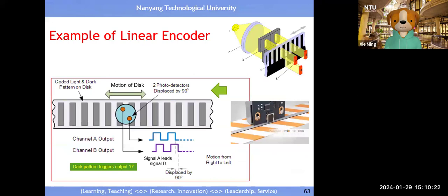Okay. Then you may want to know how to have a sensor which allows us to measure linear velocity, right? Then your design is like this, right? Same, okay? So then you will have a light emitter, light receiver, right? So you have a vertical strip, okay? You have transparent and opaque. Transparent means what? The light can pass through, right?